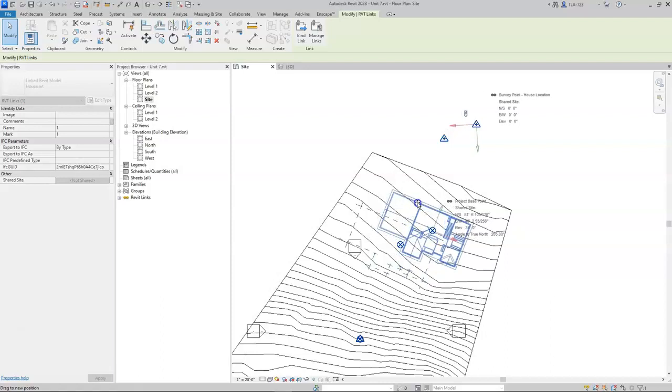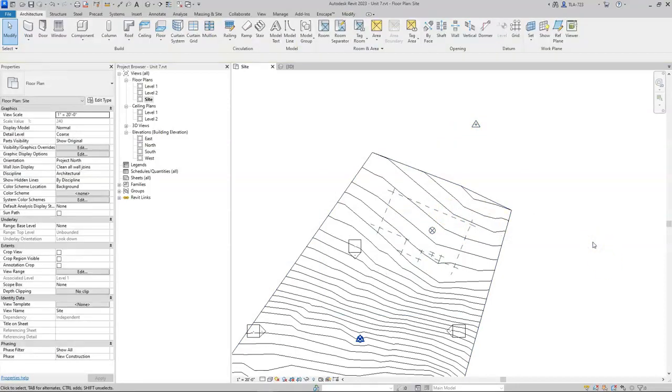We're going to have this thing set maybe 20, 30 feet back from the edge of the property line. Close enough. If we wanted to get it more accurate than that, we could certainly use a combination of detail lines or reference planes to do that. The next step is to move the house vertically so it pokes up out of the ground just enough, or about where we think we're going to want it vertically. This is actually, in reality, a pretty critical step because making sure that your house aligns and is vertically at the ideal spot within the existing topography is going to reduce a tremendous amount of site work and dirt work that needs to be done.